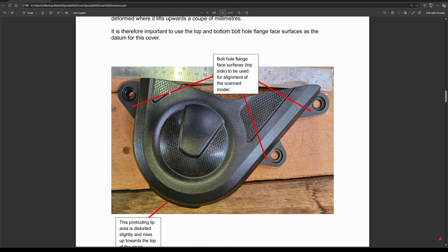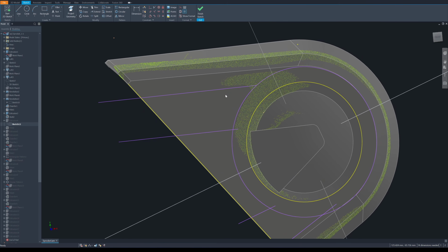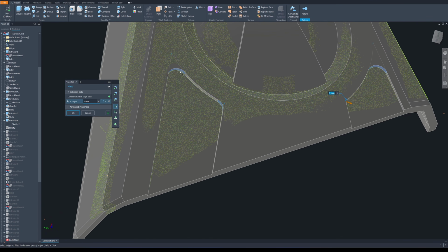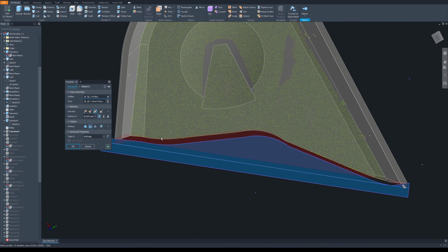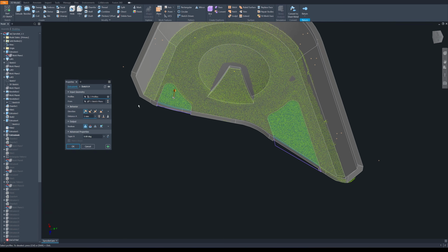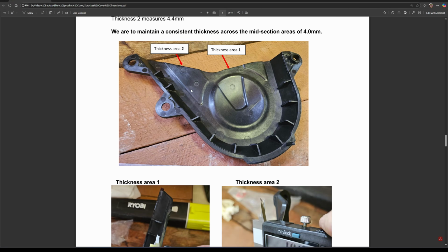Okay, in the front side there is a pocket, 1 and 2 here, that I need to cut. So I use a sketch and trace it with the point cloud and create this cut. And then I use a fillet command. I create a sketch by tracing along the point cloud, and then I cut it. And next, I'm going to give an extrusion from this imprint. See, extrusion from the inside.